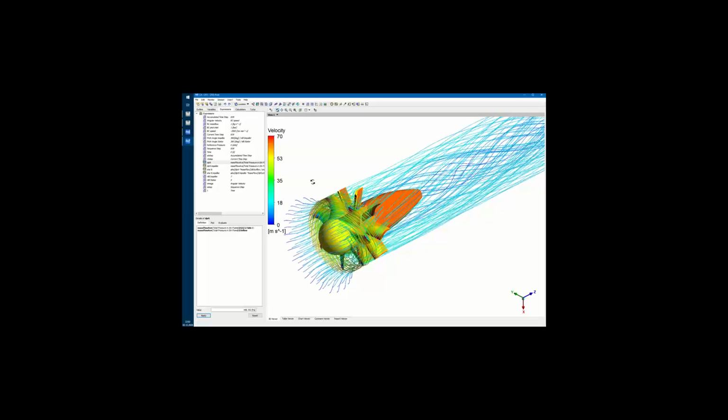We import a CAD file, a STEP or Parasolid file, for example, to CFturbo, or it could also be STL data, so we can read it in, and then we rebuild the model. This is a bit of manual work, but we can rebuild it, right? And then bring this rebuilt model to Ansys as we have seen it here today. It's a possibility, and we are in a process of making this more and more user-friendly and comfortable. But in general, it's already possible, yes.